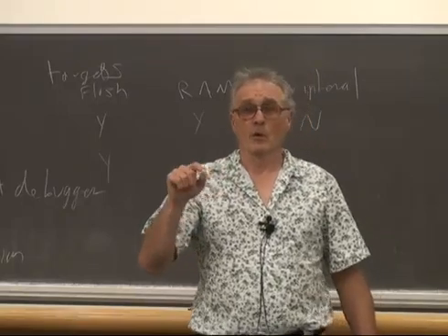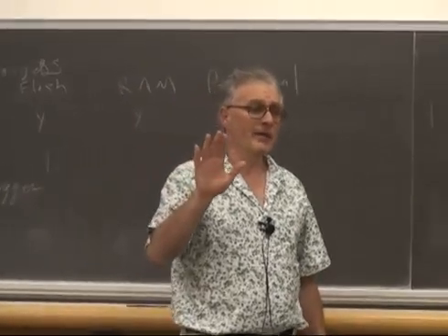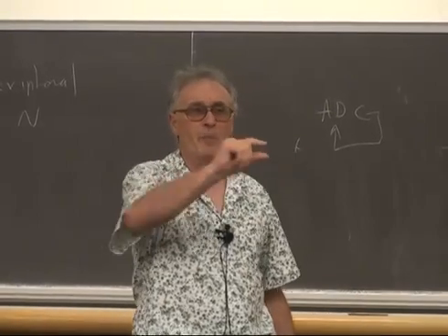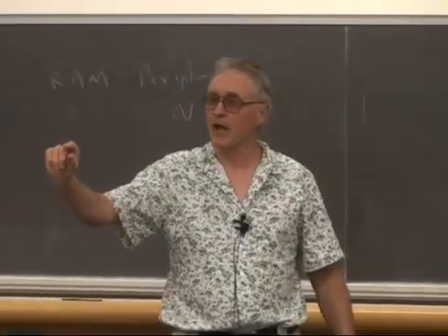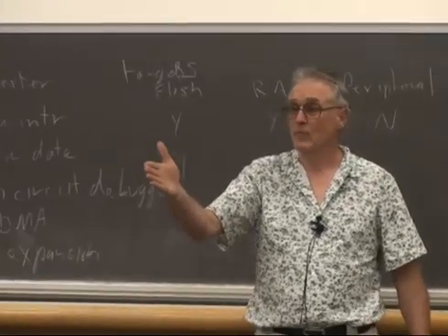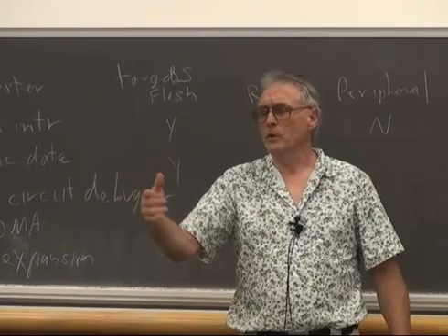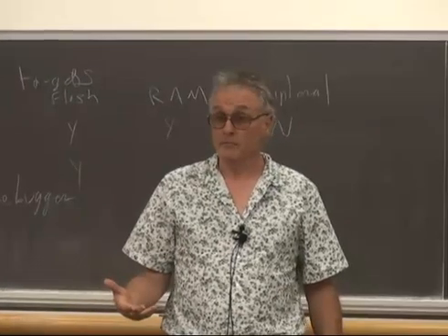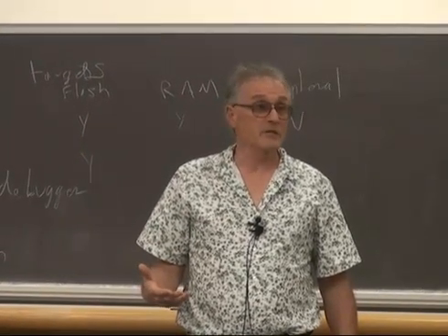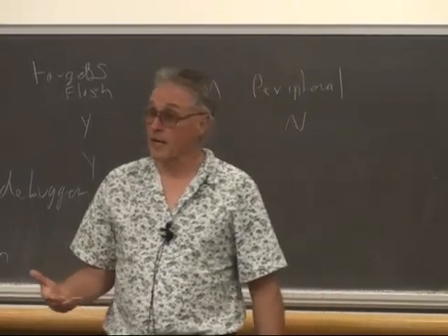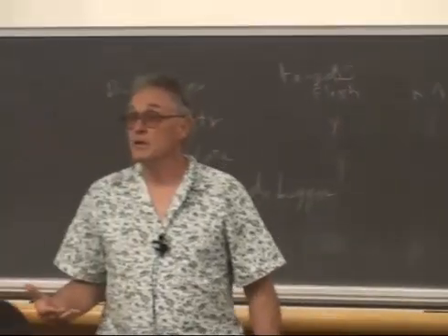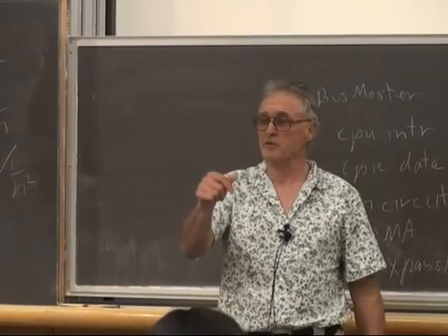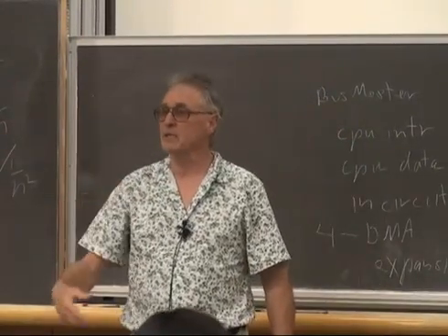Yes. You can also end a DMA transaction on a pattern match, so that if one of the bytes it's reading out of memory happens to have a certain value, it stops. So you could use, for instance, if you were transmitting a string that you didn't know the length of, then you could stop on the 0 that terminates every string in C. So this, to me, is specifically set up for stopping string transfers. You start the string transfer, you go do whatever you want, it stops when it's done.